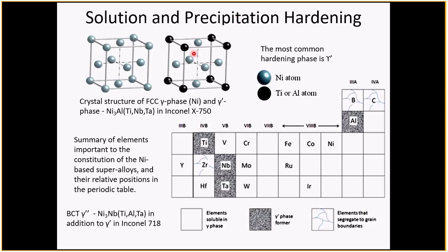dislocation gliding through this ordered phase, you can well imagine, this would be gliding on a 111 plane, typically, in a 110 direction. Sorry, I'm mixed up. It's a 110 direction.